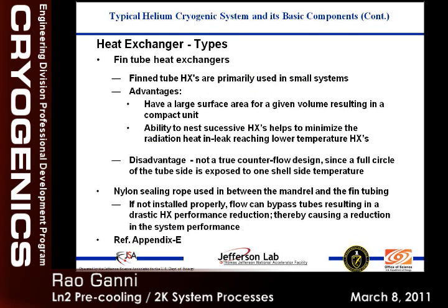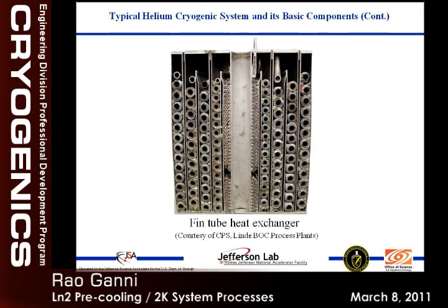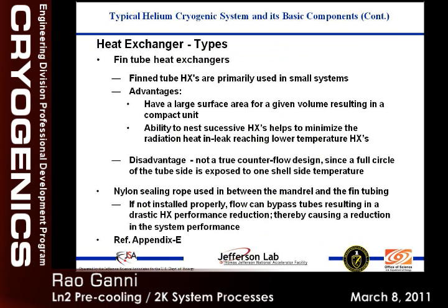And if you look at it, it is not a true counter flow because the flow on the high side is going round and round, whereas the low side is going through. So each one round is getting a different temperature. So this is not a true counter flow, it is pseudo counter flow. So you have to add the effectiveness. If you calculate on a true counter flow, you will not get there. You have to add another 30-40% more turns to get to that effectiveness.